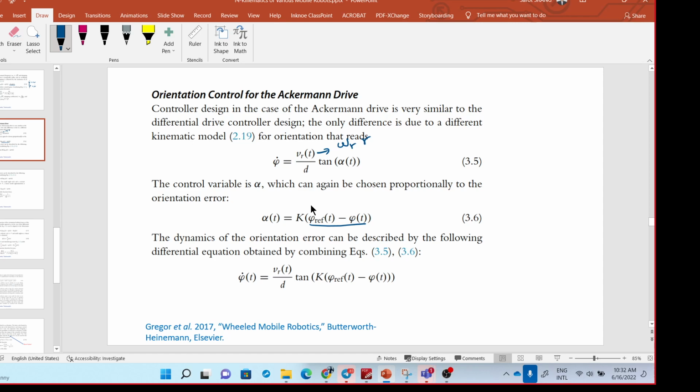Let's say the steering wheel has another actuator motor to steer it. So we just command alpha d into the actuator with the control hardware there, and then the actuator surely turns the actual alpha to be the same as alpha d.